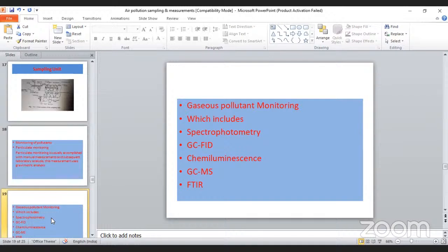For that, any instrument is supposed to satisfy the calibration. When we follow the calibration, how do we have to do it? You have to analyze a sample of known concentration. When we do the analysis with the known concentration, it should give the exact concentration.